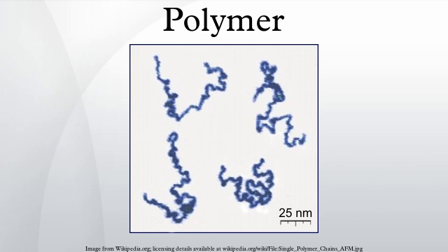Glass transition temperature: a parameter of particular interest in synthetic polymer manufacturing is the glass transition temperature, at which amorphous polymers undergo a transition from a rubbery, viscous liquid to a brittle, glassy amorphous solid on cooling. The glass transition temperature may be engineered by altering the degree of branching or cross-linking in the polymer or by the addition of plasticizer.